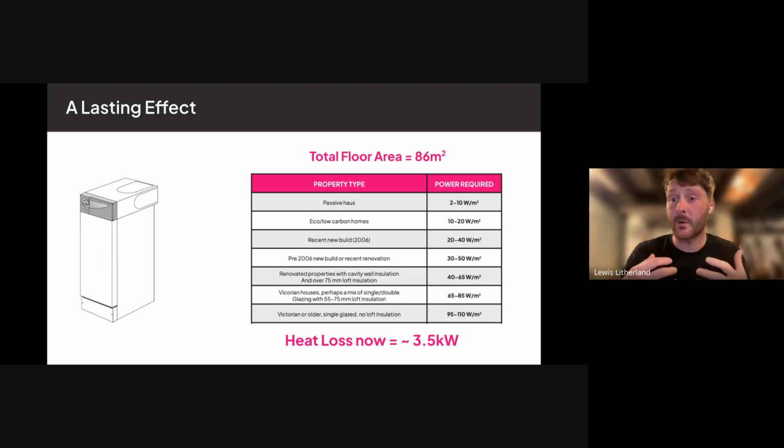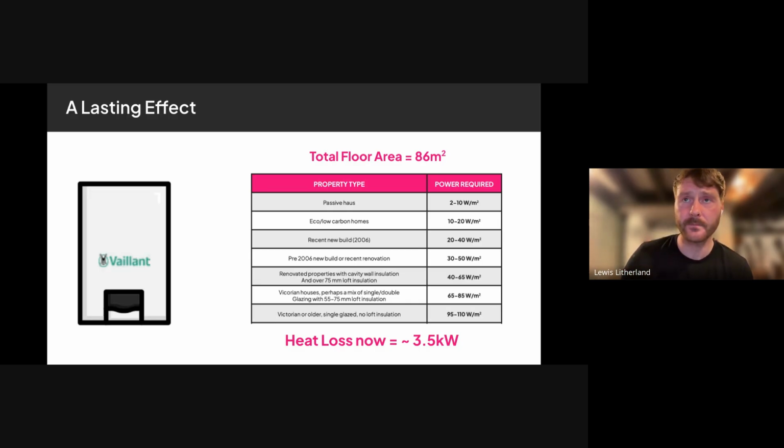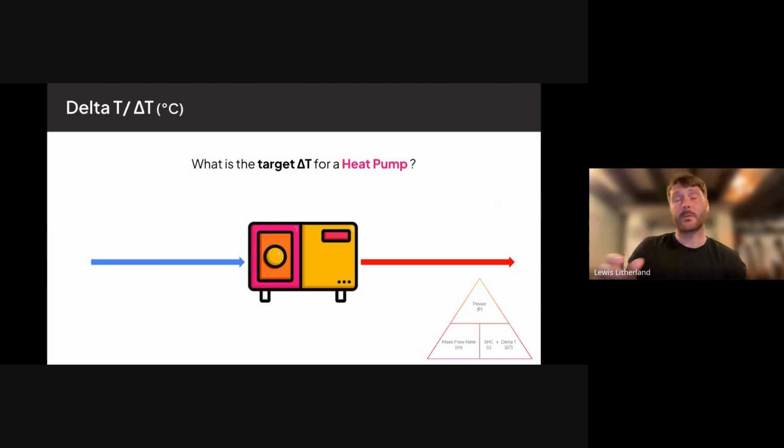And again, for heat pumps it's actually a really good thing on older houses, which is weird to think about, that the older houses actually need less work than a newer build property, which probably has rads that are not sized properly. That's why they're little postage stamp things that look awful. It's a weird thing to think about, that by not doing it right, we've actually helped ourselves transition to heat pumps moving forward. So that's why we're talking about this now.